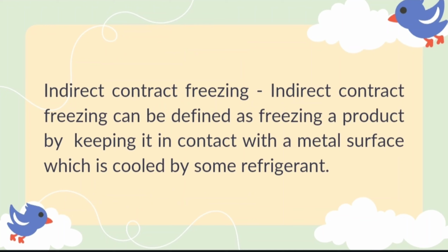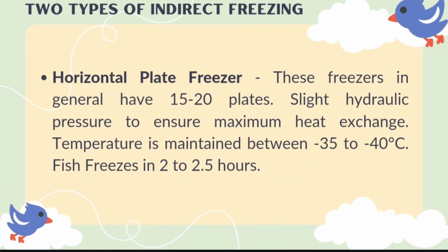Indirect contact freezing. Indirect contact freezing can be defined as freezing a product by keeping it in contact with a metal surface which is cooled by some refrigerant. There are two types, the horizontal plate freezers and the vertical plate freezers. Let's go first with the horizontal plate freezer.